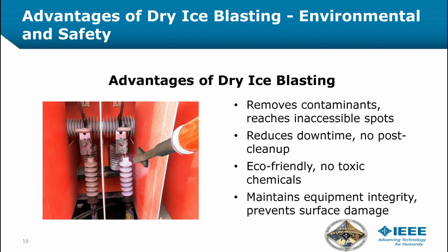The advantages of dry ice blasting: it removes contaminants, and it reaches inaccessible spots that you could not possibly get to. It reduces downtime, no post-cleanup. You don't have to clean up anything afterwards. It's eco-friendly, it's non-toxic. There's no chemicals used. It maintains equipment integrity and prevents surface damage.